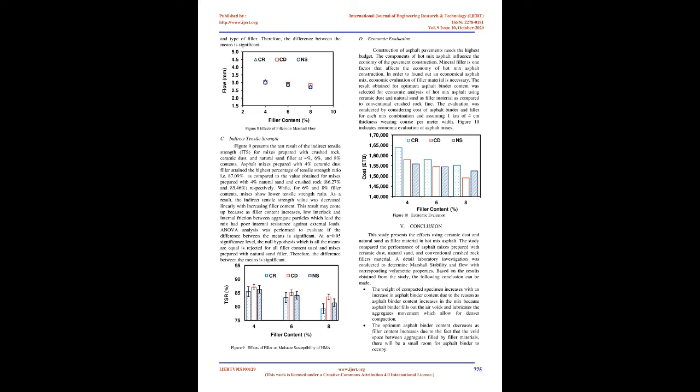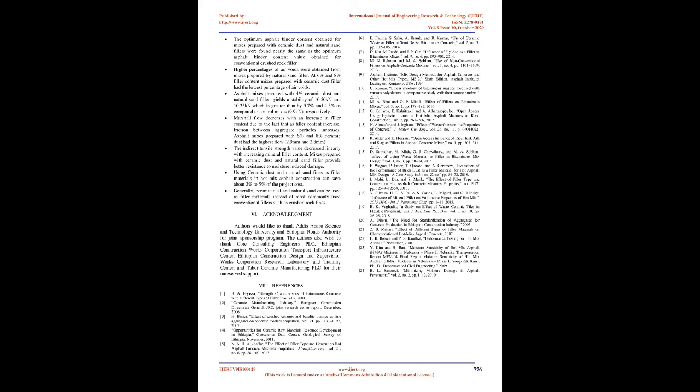ANOVA analysis was performed to evaluate if the difference between the means is significant. At α equals 0.05 significance level, the null hypothesis, which is that all the means are equal, is rejected for all filler content used and mixes prepared with natural sand filler. Therefore, the difference between the means is significant.